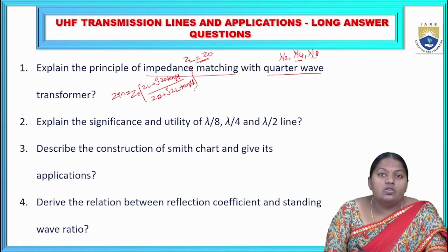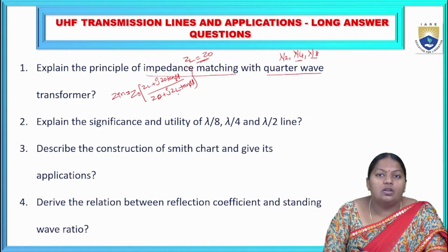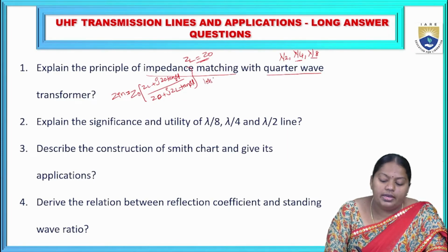If the attenuation constant alpha exists in the equation, then there must be some loss in the signal, and the lossless line becomes a lossy one. Here, it consists of only the imaginary part, meaning there is no attenuation constant. Hence, the equation resembles a lossless one. So this is the input equation for the lossless transmission line.